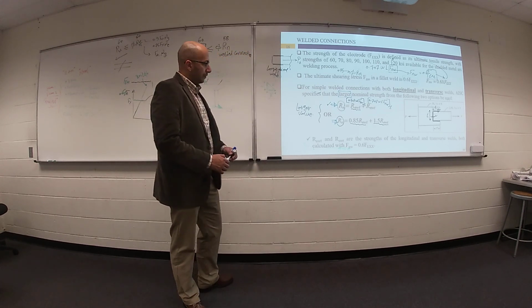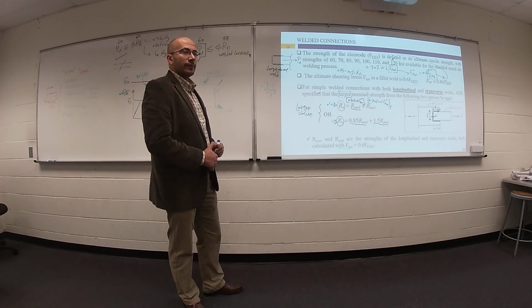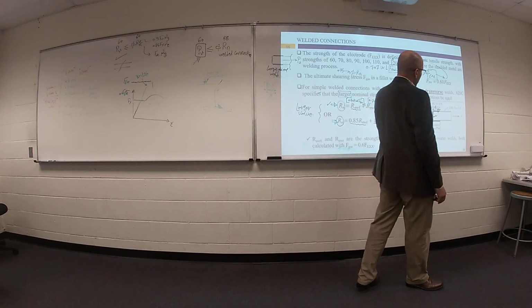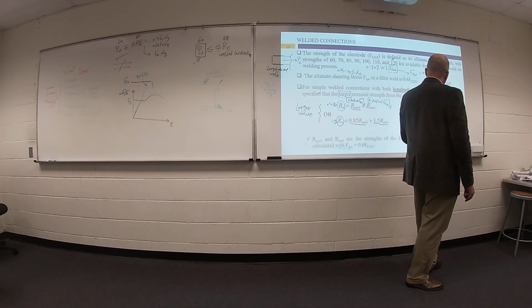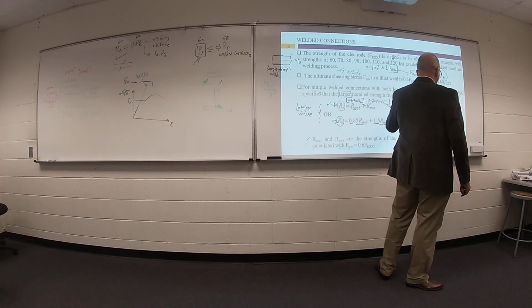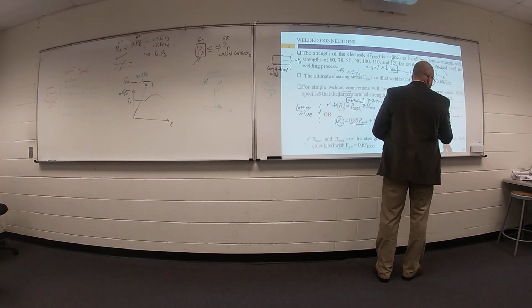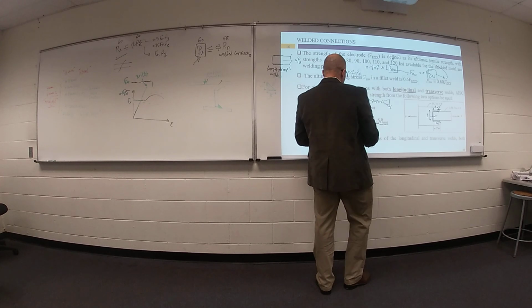So on the longitudinal one, do we use 6 inches for the L? Yes. Which 6 inch? Yeah, the longitudinal ones, you have 2 welds that are 3 inches each? Yeah, you have 3 inch here and another 3 inch here. So your L will be 6 inch.